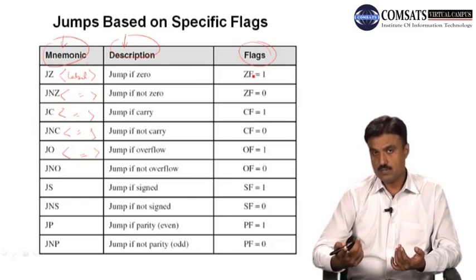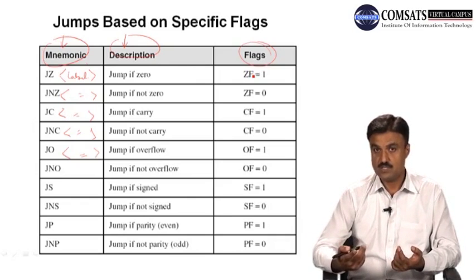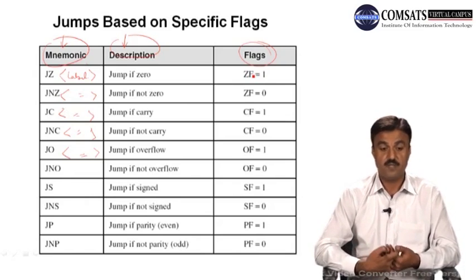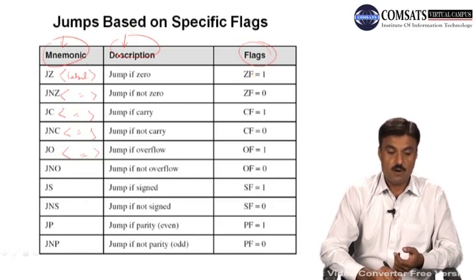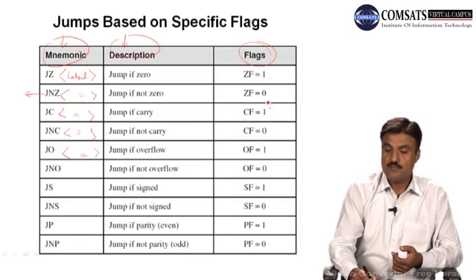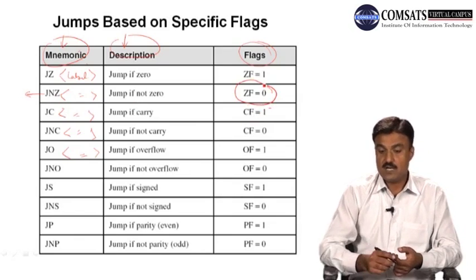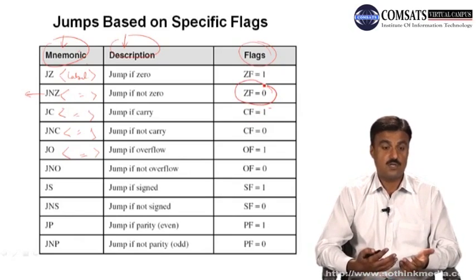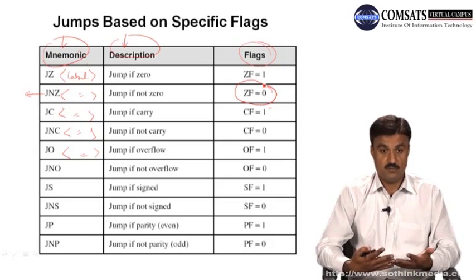And maybe you saw that in our previous program we used jump and zero when we used compare and other instructions, the compare instruction especially. The other instruction is jump not zero, so you can extract the definition from here. Jump not zero: if the zero flag is unset, or is not set, or low, or 0, then this instruction will jump to the label.